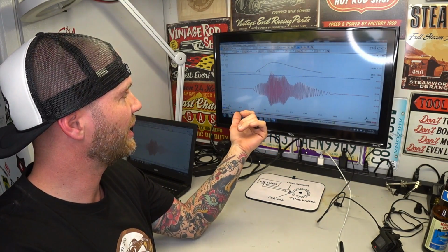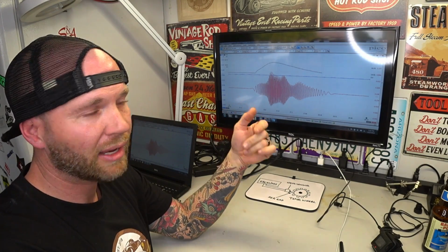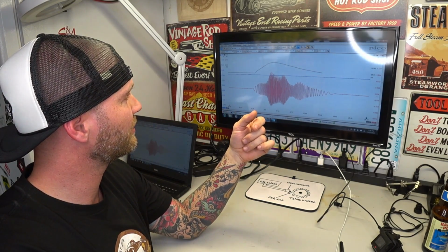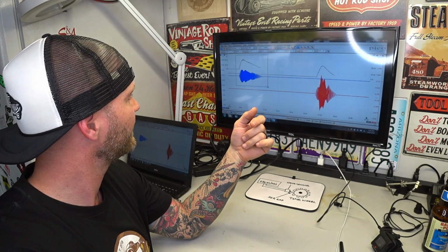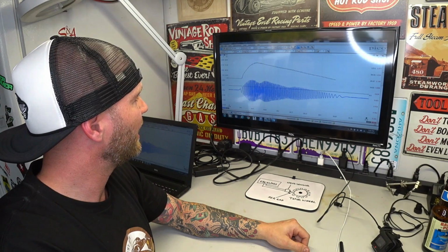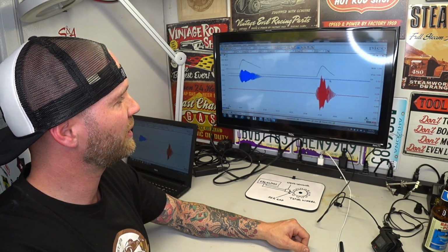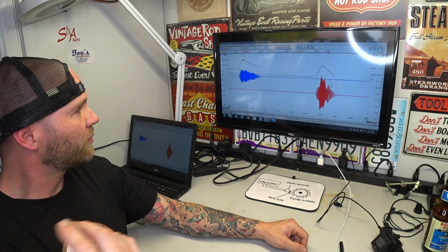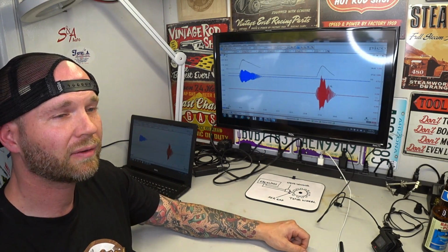If this is showing good, then the electronic brake control module is not going to see an issue. It doesn't see an issue with this one, and the frequency math channel does not see an issue with the other one. So right there, that's a fix. New rotor took care of that issue.